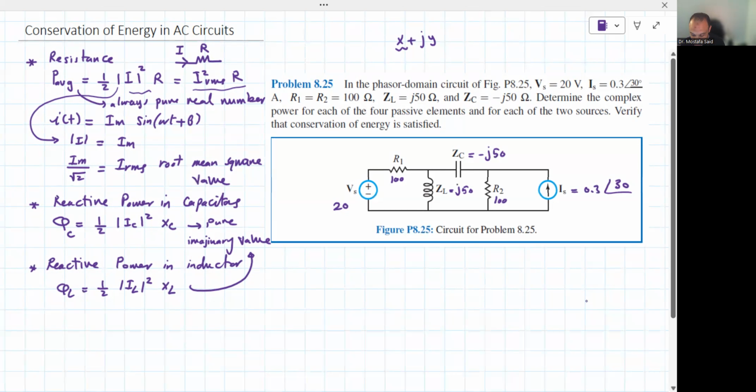So the best way to solve this circuit is to use nodal analysis. We have here 3 nodes. Let's call one V1, another node here V2, and another node here. But in nodal analysis, we usually choose one of them and make it ground, usually the one in the bottom. Can you use any one? Yes, that's up to you. We're going to choose this one in the bottom as our ground, and let's solve the circuit.